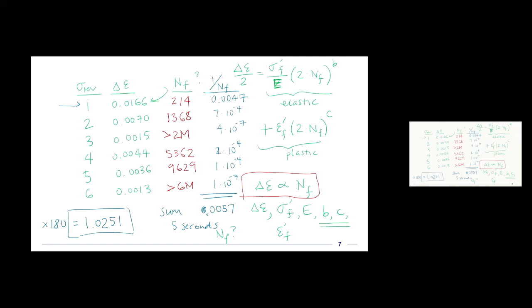So this expression that we used up here at the top, which summed the elastic and plastic terms, is based on fully reversing, 0 mean stress and 0 mean strain. Okay? And so for some of these, it's very accurate, like for some of these down here maybe, because their mean stress is close to 0. It does not really capture some of the other sections, especially the ones with really high mean stresses.